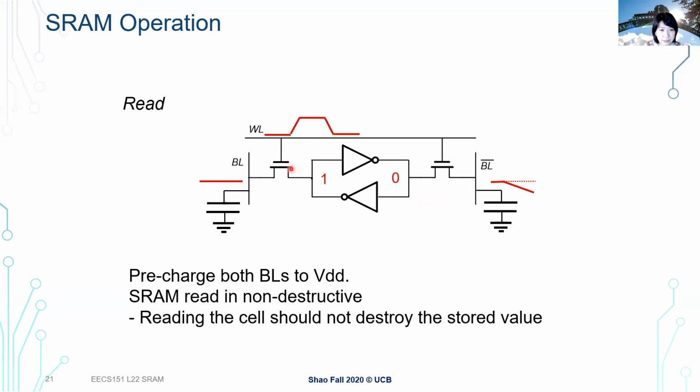Let's say in this case, if you look at the one on the left first, my gate voltage is VDD. Drain to source, my source voltage is 1, my drain voltage is also 1, so there is nothing going on. So this is always 1. There's no charging and discharging going on here. But if we look at this access transistor here, my gate voltage is VDD, and let's see, drain to source. My source voltage is 0, and my drain voltage is VDD, which is 1, right?